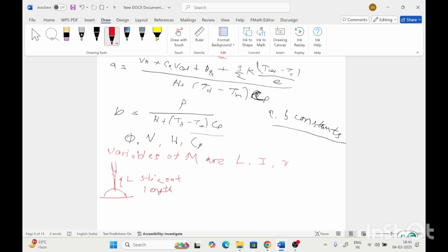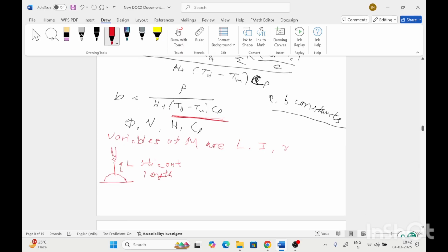And this term we require to increase the temperature of the droplet for the detachment of the droplet. This is required because as the material melts, the droplet forms, and the droplet will only detach from the electrode when the droplet temperature is higher, so we have to superheat the droplet to a higher temperature to release it.